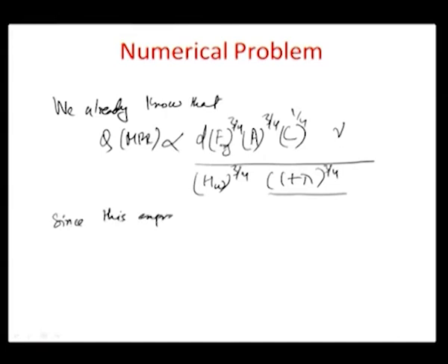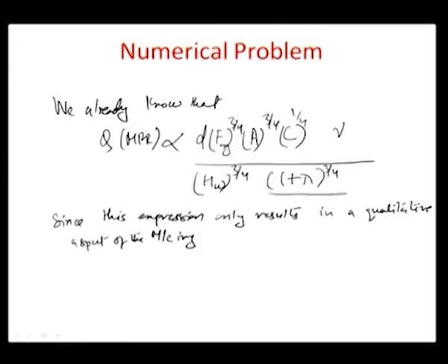Okay. So since this expression only results in a qualitative aspect of the machining process, for sake of simplicity we assume that the volume removal per grit indentation can be approximated by hemispherical volume.